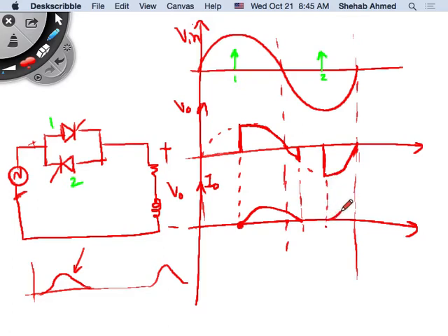So here I have to go down to the current and draw the current waveform, right? It would have stopped here if it was a resistive load. If it's not a resistive load, it will continue. I can go back here, and because I'm drawing one cycle, I flip over, right? I start over again. So it will start here. The extinction angle will be somewhere here. So the waveform will look like this.